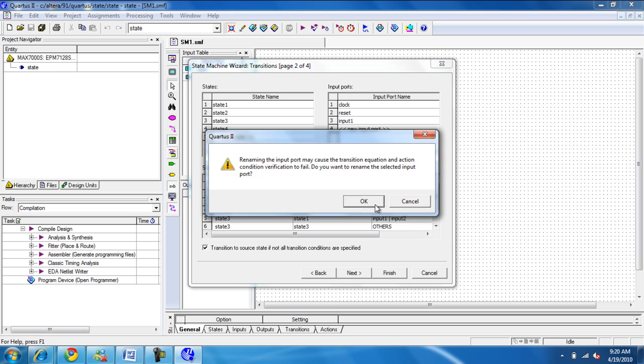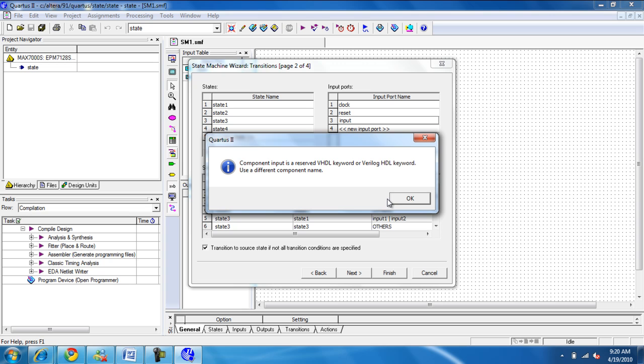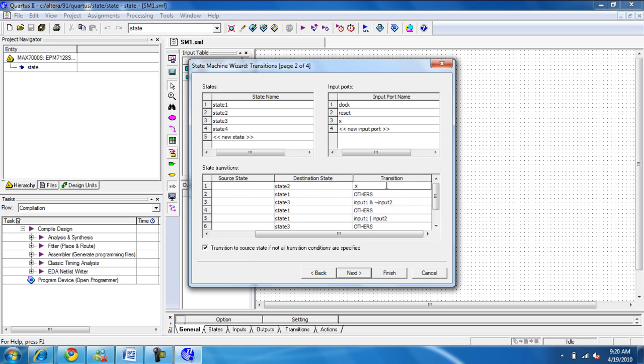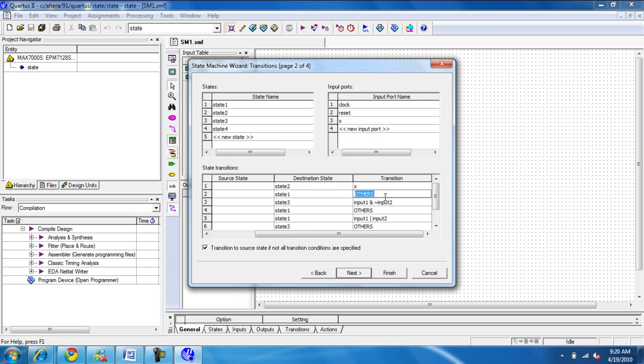You will worry about how many inputs you have. You have 1 input, you have 1 reset, you have 1 clock, then you have 4 states here. Then the rest of it is now trying to understand how those relationships are defined. And you can rename this thing to anything you want to. In this case, I'm just changing the input name to X, so it will reflect what we had on the table, and the states can change to anything you desire. So you can rename them to whatever you want.